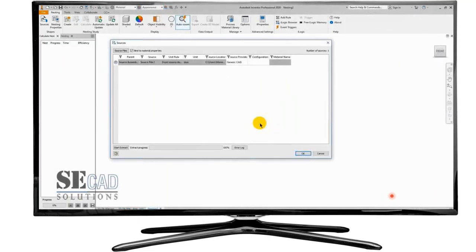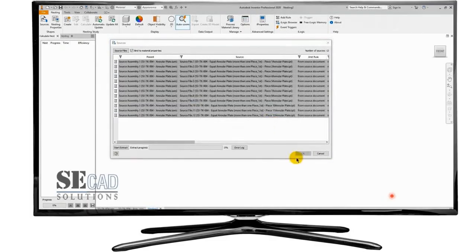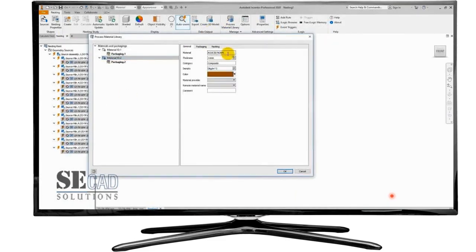Okay, now this tool of Autodesk will detect the thicknesses and the material for all plates, and if there is a different material or different thickness, it will separate it on a different sheet plate. Now, after importing this one, we will define the available plates in the stock from the market.